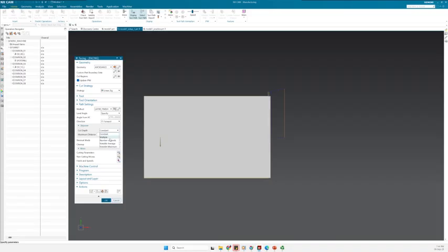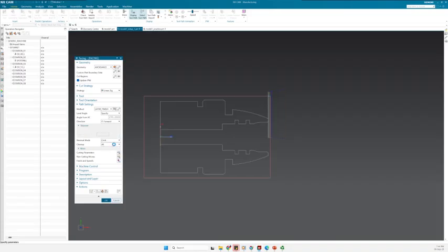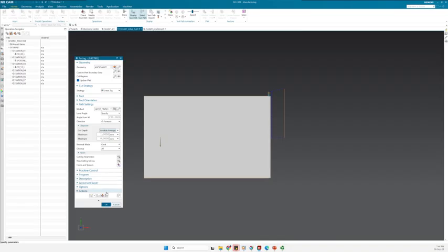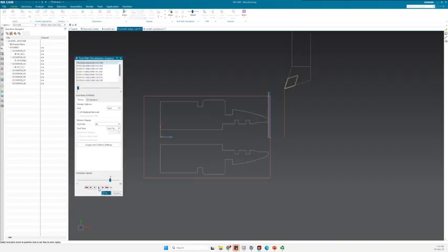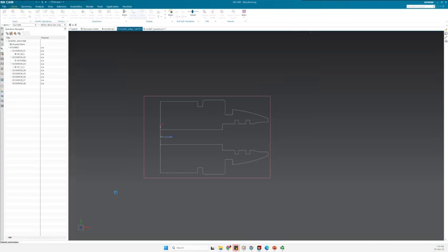So this is, for example, this one. And now I can see how that generates for me. So now I will have more cutting paths. I have a very small depth of cut, and it takes 4 times. Maybe it's good, maybe it's not. It really depends on your cutting scenarios, what you are deciding based on the drawing and specification of your component.